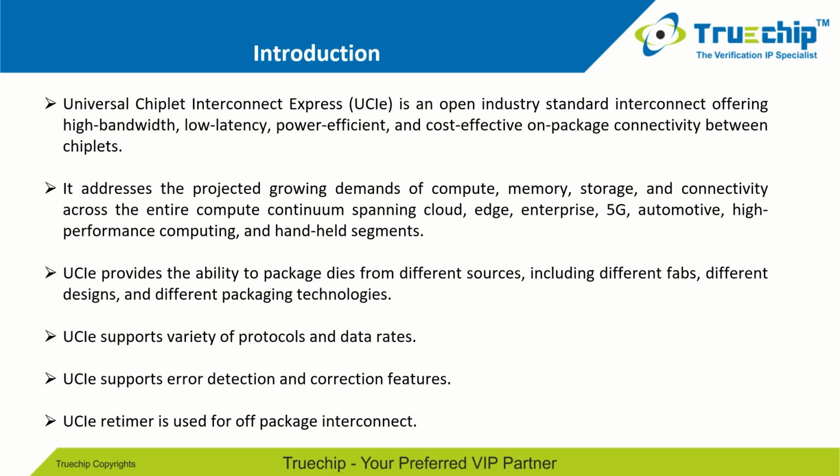UCIe provides the ability to package dies from different sources, including different fabs, different designs, and different packaging technologies. UCIe supports a variety of protocols, data rates, error detection, and correction features. UCIe is also used for off-package interconnect using the UCIe retimer.